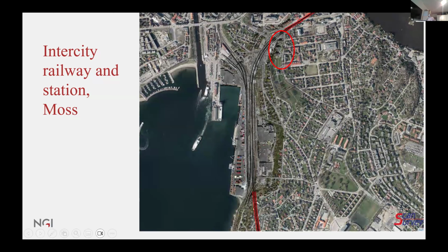And we had arrived at 12 millimeters, and 17 millimeters was our prediction where the landslide would occur. So with the information, we redid the probabilistic analysis, and we came to a probability of failure of about 10%. So within 1 week, we had to evacuate these 3 buildings here, which was very unfortunate.